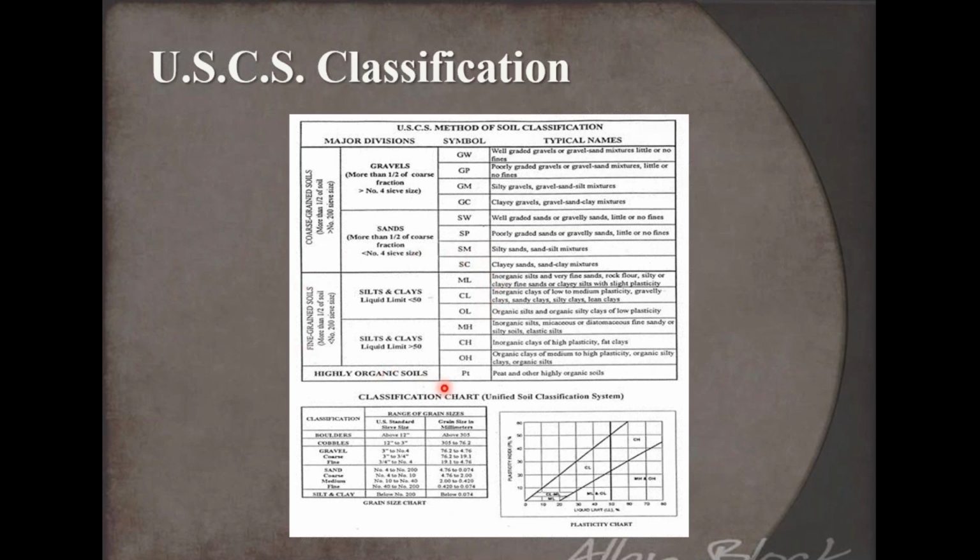What I want to just point your attention to here a little bit is the clays. We've got that liquid limit, less than 50, greater than 50, and that is the difference between your lean clay or a fat or heavy clay. And obviously, when you're talking about clays, if it's more of that lean nature, under 50, those can be suitable for construction activities. Anytime you're getting into a liquid limit higher than 50 and you've got that fat, heavy clay, we're looking at material that's probably going to have to be fixed or removed from that job site.